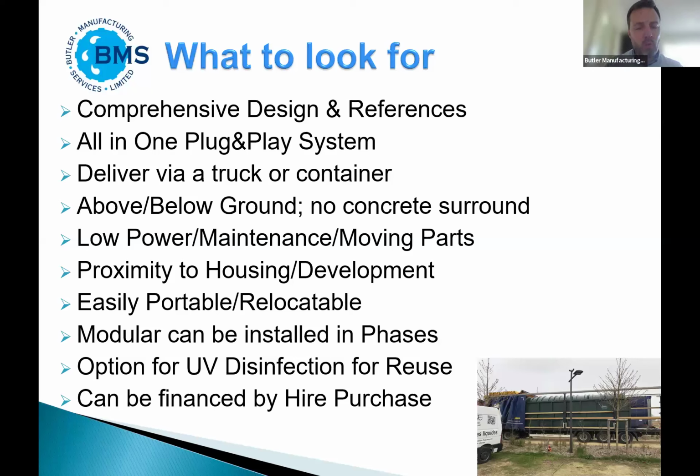For temporary sewage treatment, you really need an all-in-one plug-and-play system that can just be brought to site. You don't have to do much civil works. It can be easily put in, just connecting the inlet and outlet pipe and electricity, and it's ready to go. And emptying it and doing a reverse, it's ready to move to another site. That can be delivered by a truck or container. The solution, as I said, can go above or below ground without a concrete surround. If it needs a concrete surround, it's never going to move from the site again, so it's really not a true temporary sewage treatment solution. And there can be big decommissioning costs afterwards if this is not taken into account.